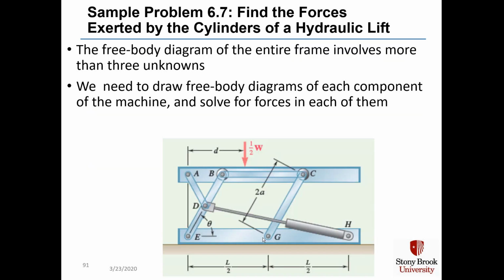Back to our sample problem. The free body diagram of the entire frame involves more than 3 unknowns, and so we'll need to draw free body diagrams of each component of the machine and then solve for forces in each of them.